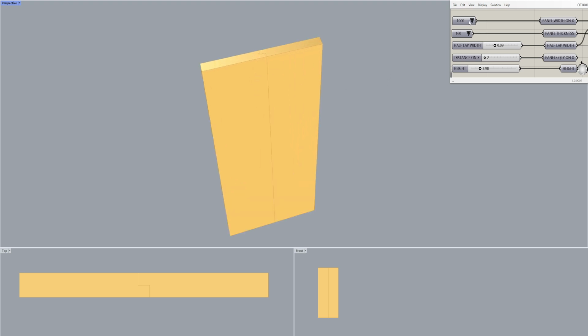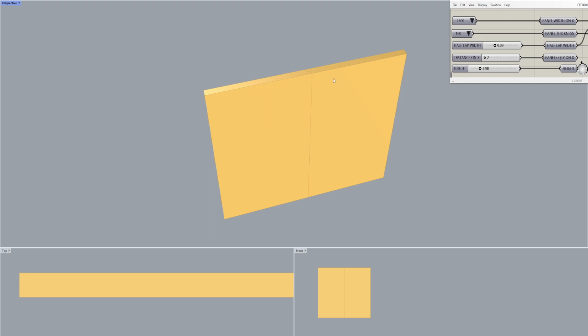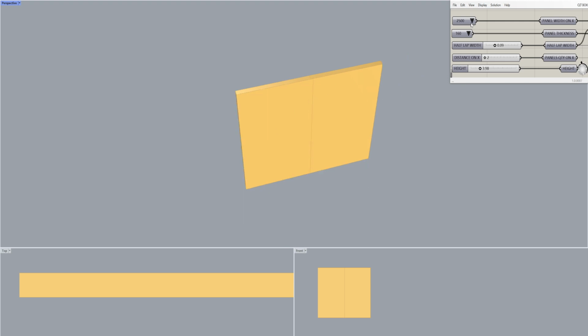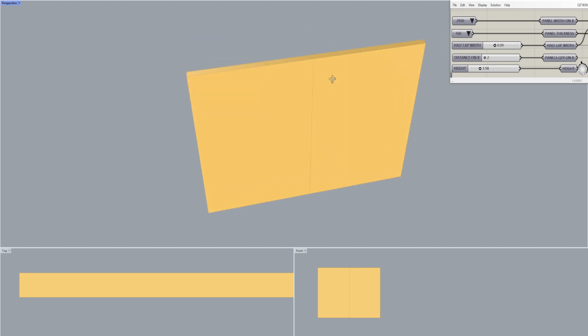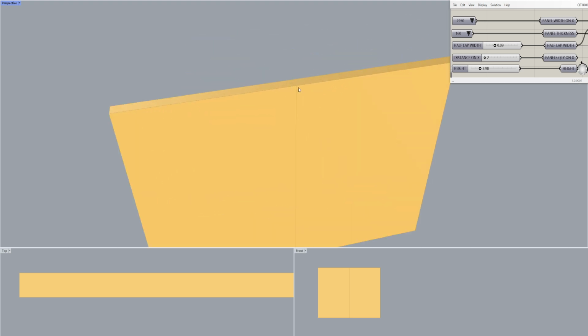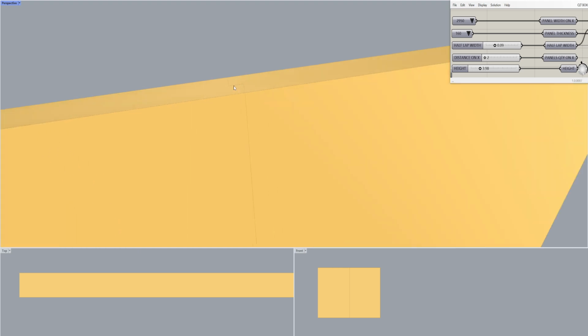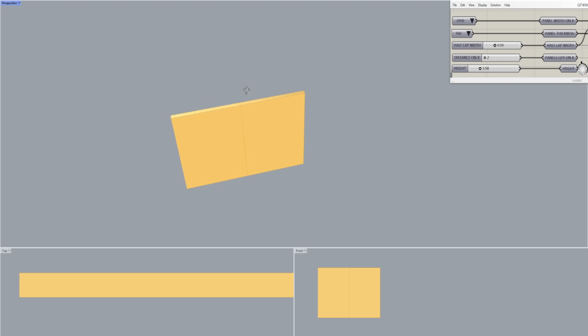Basic two panels here, and then we can modify the panel width. So let's say we want to use 2.5, so it's just working. You can't draw a straight long line here. It's only working off of standard widths. And kind of the idea behind the standard widths here is that this will fit into a larger mother panel with little to no wastage. Of course, you have the wastage from the half lap, but we're looking at more of the optimization of things.